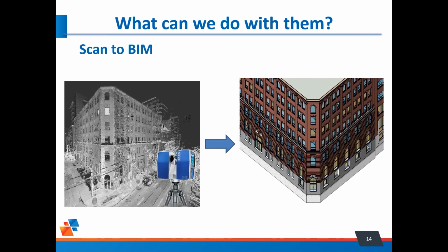Scan to BIM. That's one of the big things we do at SolidCAD, and I'm involved in this quite a bit. So I'll go out to site and take one of the scanners, and depending on what the project is, I'll decide whether I could maybe use Matterport. If it's an interior job with a lot of small rooms, I can use Matterport. For instance, I did a residential project that was 9,000 square feet. I can take the Matterport in there, and in half a day, I can do all the scanning and come up with a point cloud that I can bring into Revit.